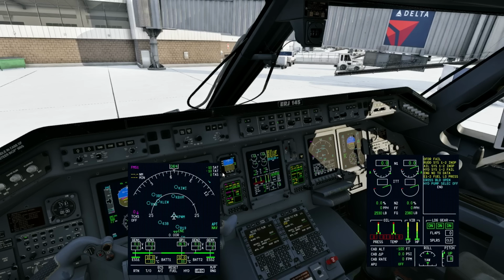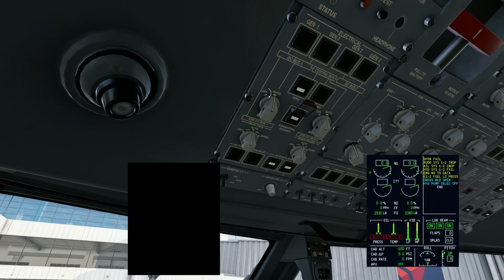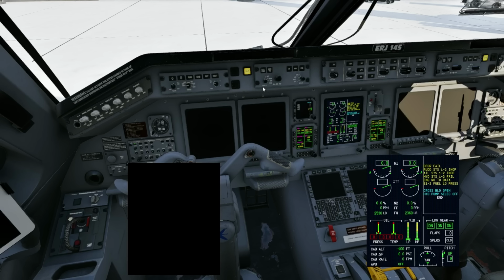However, if it doesn't go into that, say there's an electrical transfer failure, all of a sudden, every single thing on this airplane, all these avionics, the lights in the cabin, the coffee maker, everything is attached to your batteries. And your battery life may be as low as like 5 minutes. So a cool feature is this button here, designed for if it doesn't transfer to essential power mode. It's guarded for a reason. We can select it, and you see that the aircraft is forced into electrical power mode.